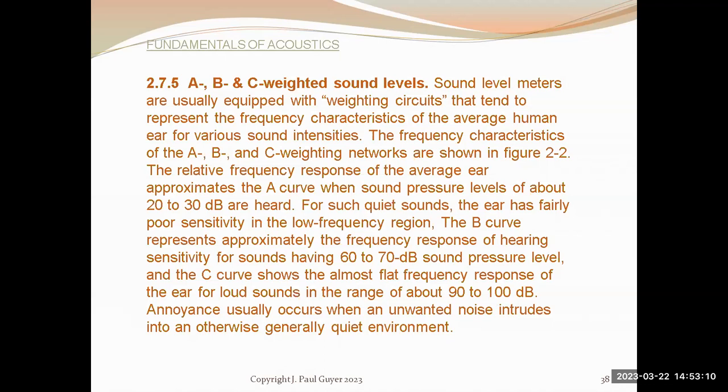The fast slow knob controls the rate at which the sound level meter samples the sound. It might sample the sound every 1 second, and so the needle on the meter shows a certain value. And then 1 second later, it may show a slightly different sound level.